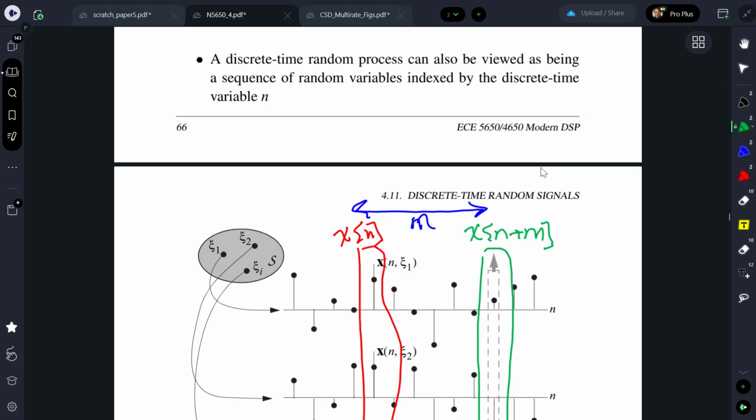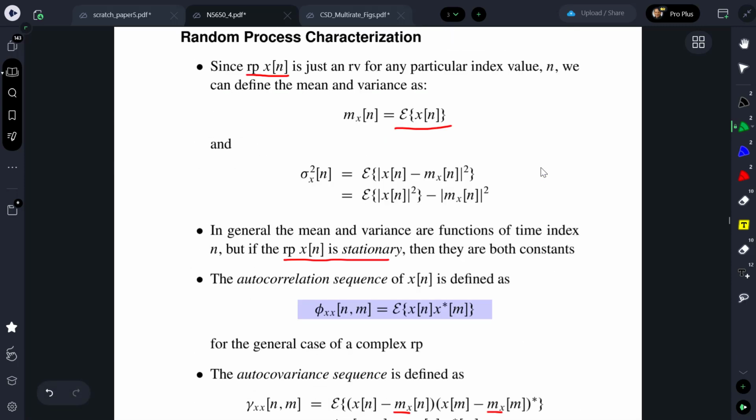Now in digital communications waveforms, that's where the difference comes in. The noise in a digital comm receiver would be wide-sense stationary, and then the comm signal itself would usually be cyclostationary because there's a periodicity associated with it. There's a clock that's running to form the data bits that are being transmitted, and that forms a cyclostationary relationship on the waveform. Not a big deal for us at all right here.